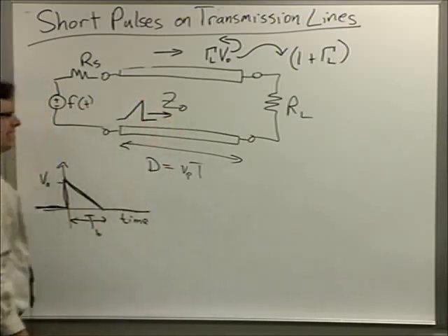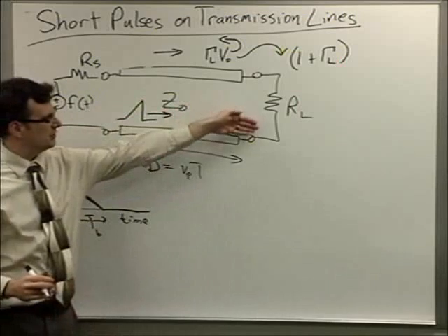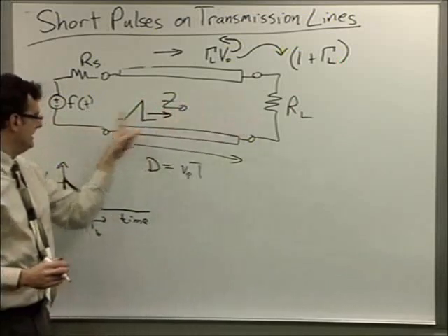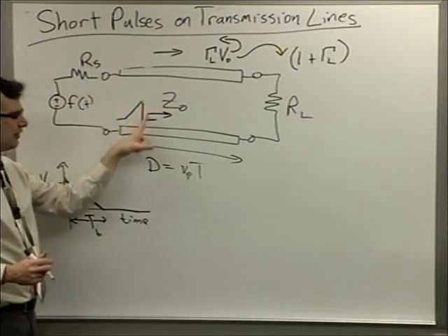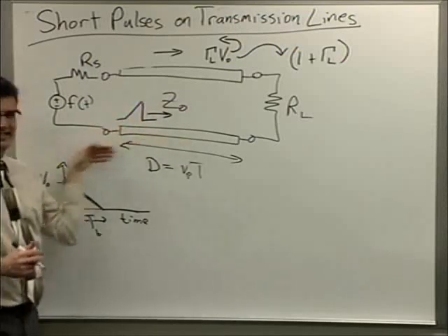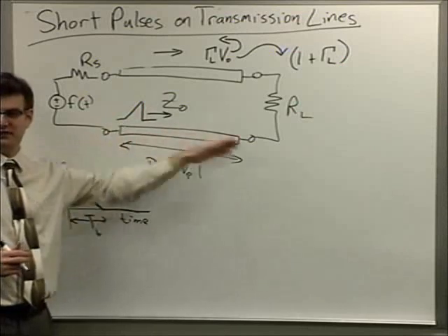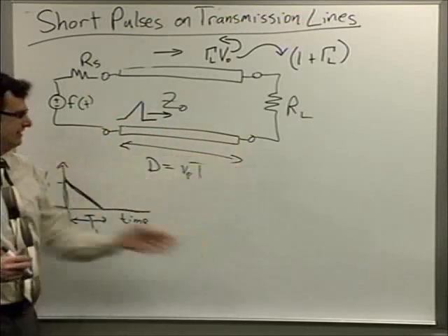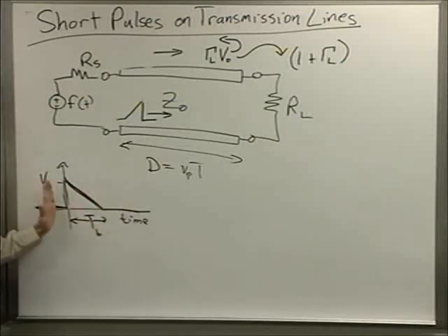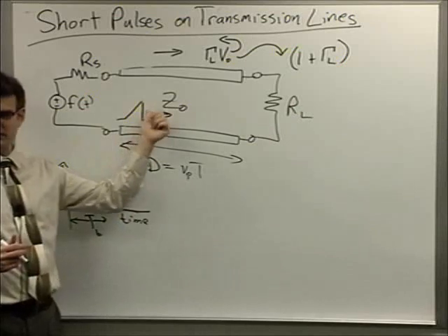The forwards propagating wave travels this way. And so the leading edge, which I've drawn in the time plot this way, has to be placed on the other side in my distance, in my graph of voltage versus space. Do you understand that distinction? This is voltage versus time, the earliest waveform, the later part of the waveform. This is voltage versus space.